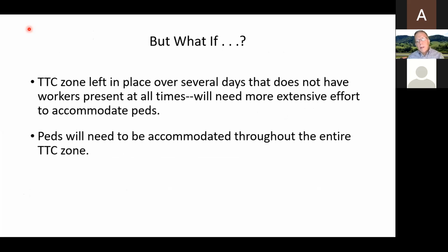But what if that temporary traffic control zone is left in place overnight or for several days? That, of course, often happens, and you don't have workers present at all times. Then we have to have more extensive measures to accommodate pedestrians. But remember, they have to be accommodated throughout the entire work zone or temporary traffic control zone.